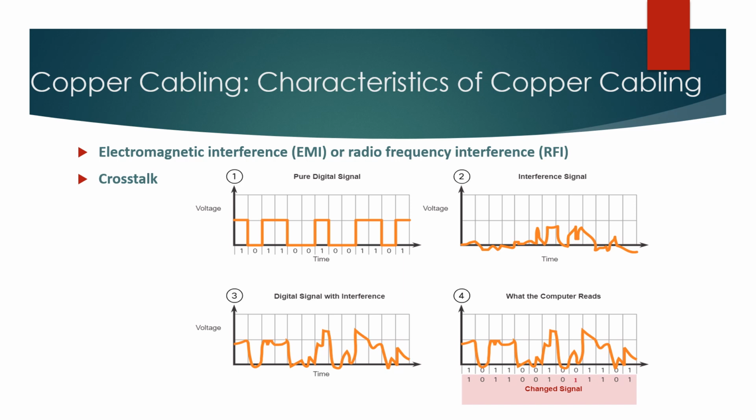The susceptibility of copper cables to electronic noise can also be limited by following these recommendations: selecting the cable type or category most suited to a given networking environment. You can design a cable infrastructure to avoid known and potential sources of interference in the building structure, or use cabling techniques that include the proper handling and termination of the cables.